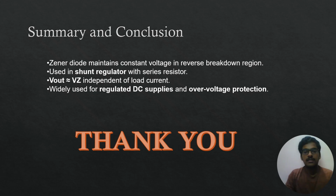So coming to the summary, we learned the following. The Zener diode as a voltage regulator works in such a way that the output voltage equals the Zener voltage, independent of input voltage variations within limits and independent of load current variations. The output does not change. This is the specialty of the Zener diode. It is widely used for regulated DC supplies and overvoltage protection. Thank you.